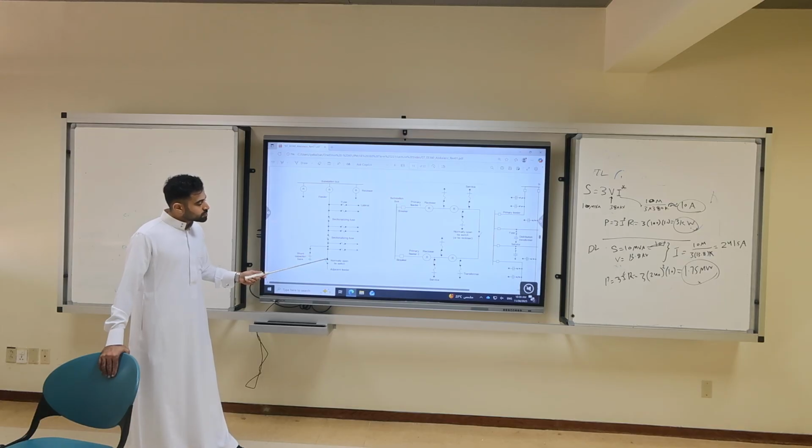This is normally open switch. Let's say for some reason the adjacent feeder needs more electricity. We will go close this breaker, and once we close it, the power comes from here to the feeder that's adjacent and support the load.